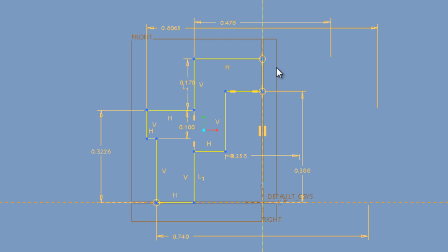So as you can see, sometimes it's easier if we have parts that are circular, that are radially symmetric, but have these sort of cuts in them that we otherwise have to create with multiple extrusions of circles, and then multiple extrusions of cuts. But we can also create that just by revolving this geometry here.